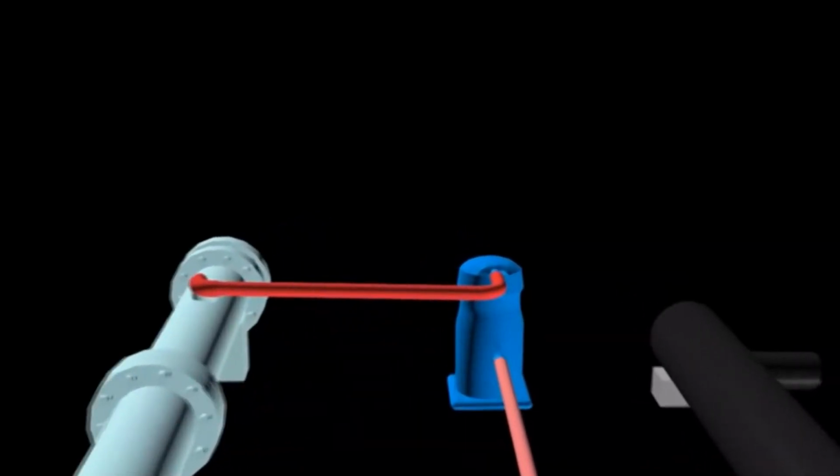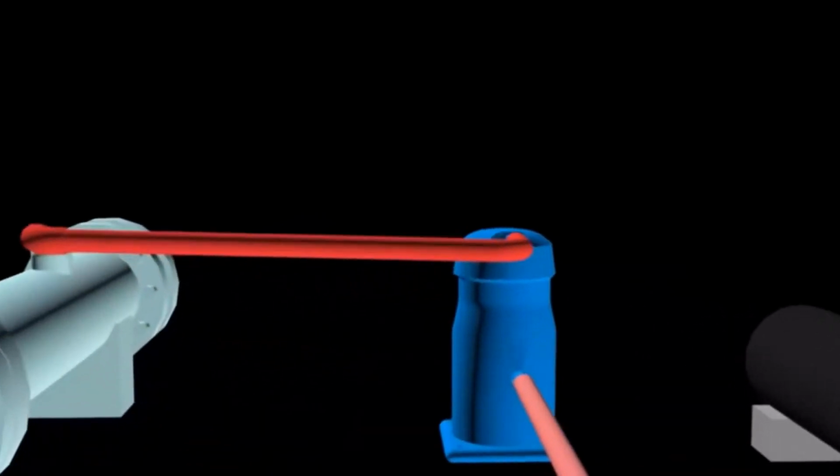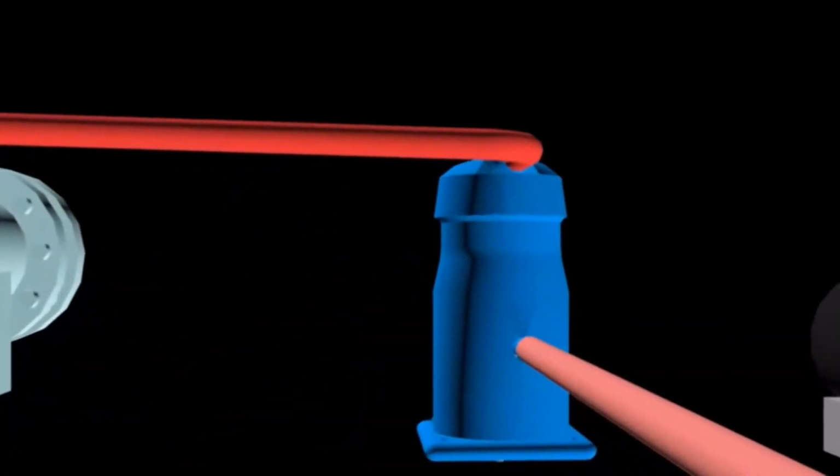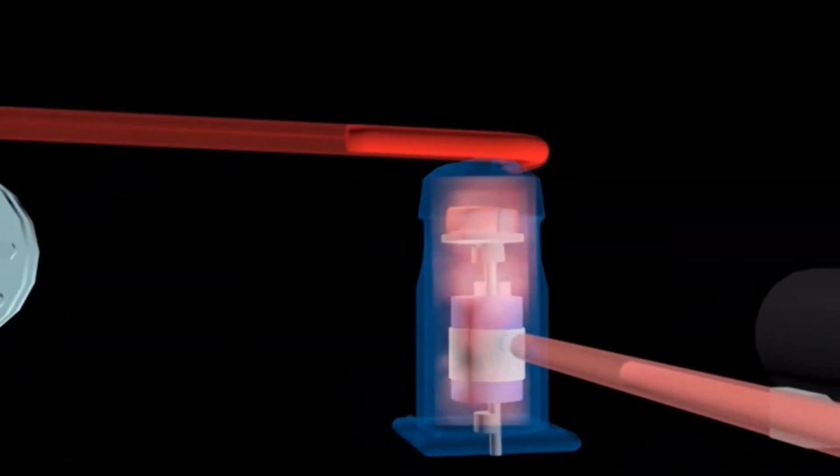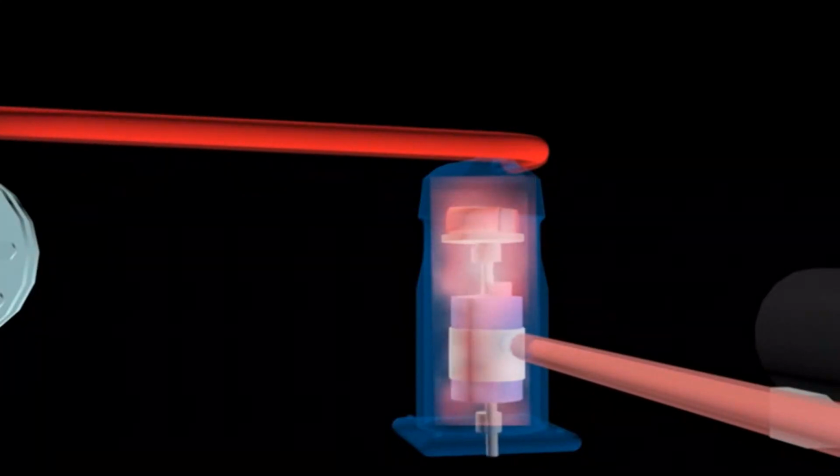Compressor. The compressor works to increase the pressure of the refrigerant. In addition, it also serves to increase the temperature of the refrigerant higher than the temperature of the condenser water so that the heat transfer can occur in the condenser. The refrigerant enters the compressor as a low pressure gas and goes out as a high pressure gas.